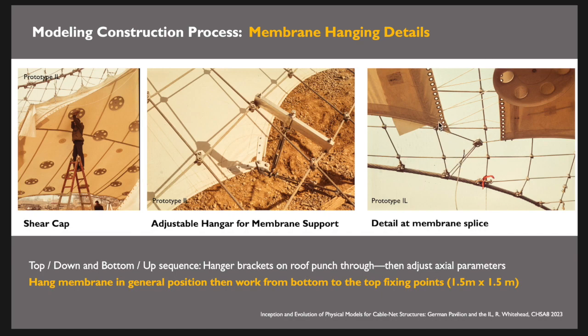I also want to get you up close to be able to show you one of these splices. These splices just have a whole series of eyelets there. You can see that the membrane itself is doubled and tripled layered because of all the stress that's going to happen on those ends. You take one end and you pull it, one end and you pull it, so that way you're sort of fixing these two ends together, holding those back to the main support cable. And then if you wanted to try to make sure that these stay tight, you're sort of pull, pull, pull like shoelaces in between.